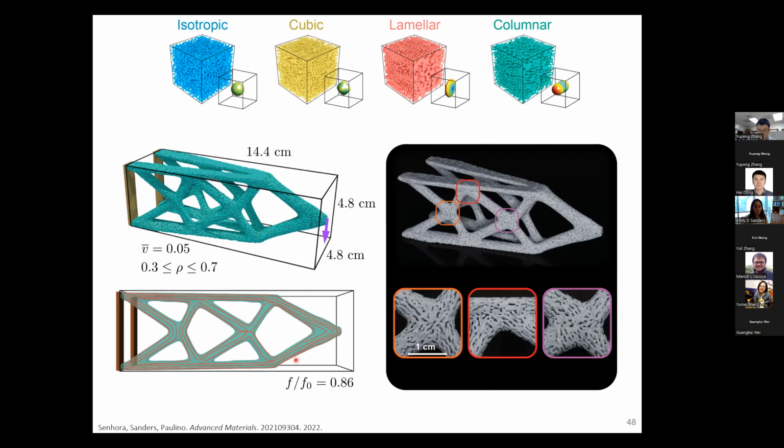So that's one thing. The other thing I want to point out here is, remember for the lattices, when we compared the lattice structures to the reference solid isotropic case, we could never do better with the lattices in terms of stiffness than we did with the reference. Here, remember, F0 is the objective function value of a solution that is made of a solid isotropic material. In this case, F over F0 less than 1 indicates that our spinodal design actually does better than the solid isotropic design.